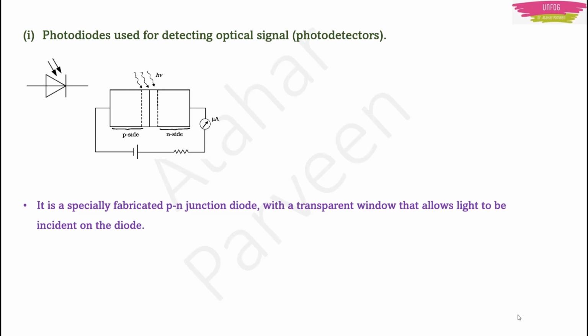So the moral of the story is that the photodiode is operated in the reverse bias condition. Why is it operated in the reverse bias condition? Because you see here in the circuit, the ammeter is connected only for a microampere. We get very small current. Small current means reverse bias. More current means forward bias, isn't it? We were talking all about this in the first lecture.